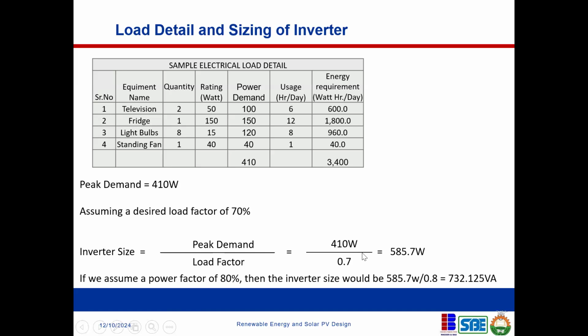Now, if you go to the market, you will likely see most inverters rated in kVA or VA. So you need to convert these watts to kVA to know what the value will be in kVA. To do this, you will need a power factor value to convert to kVA.